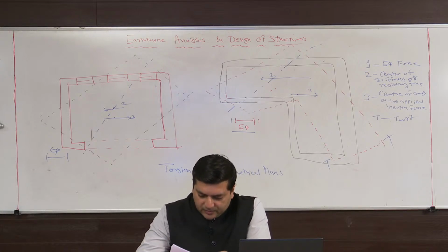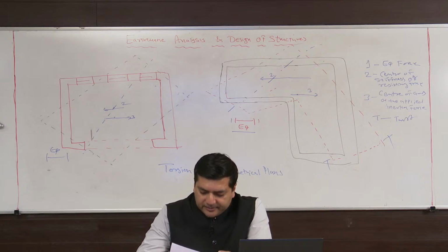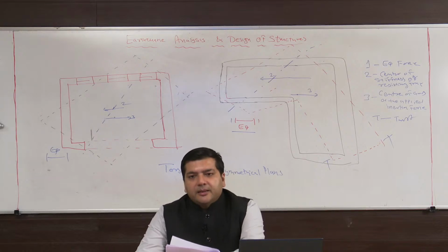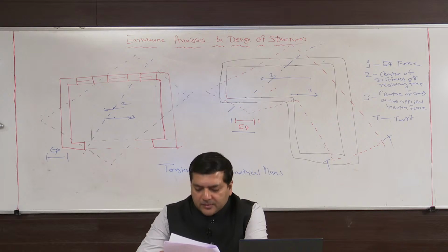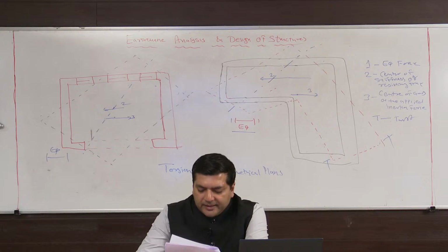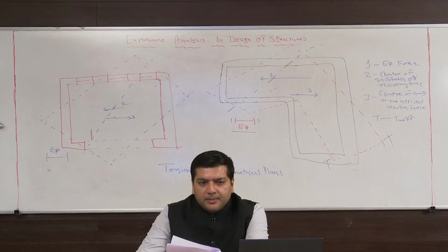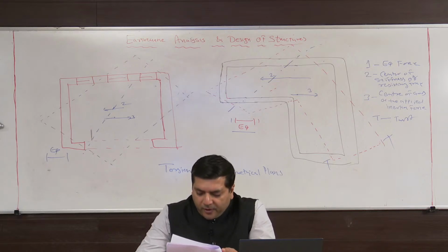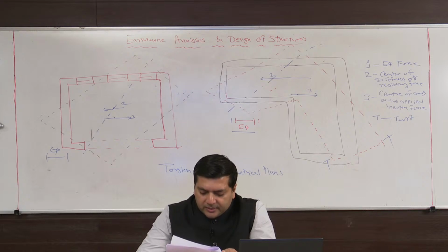Now write down. While designing the building for earthquake resistance, attempt should be made to locate the building masses and structural elements uniformly in the layout.